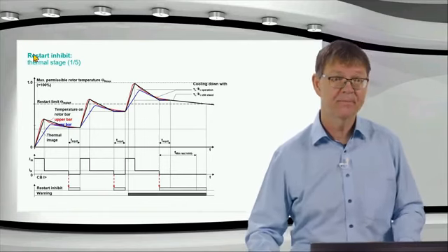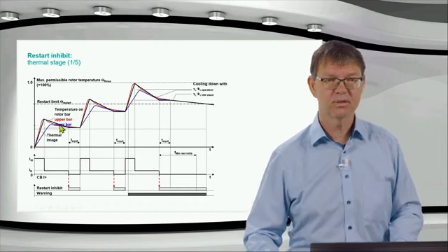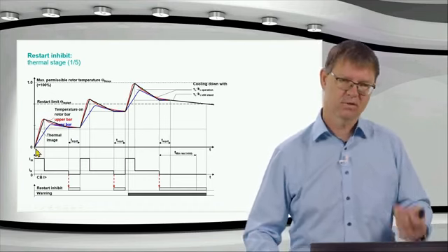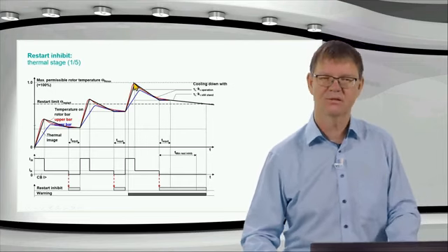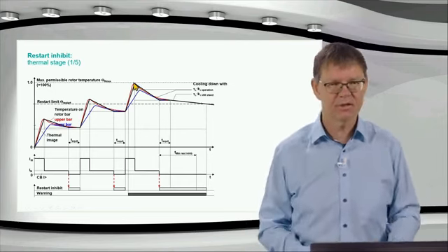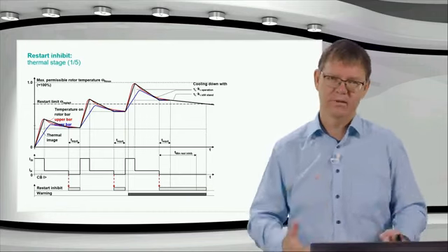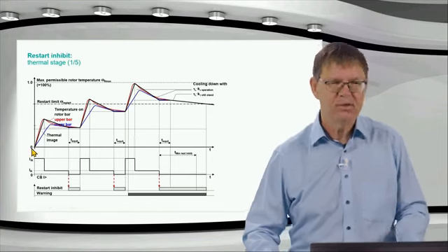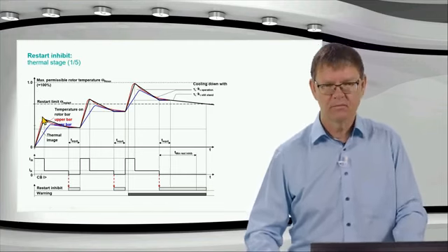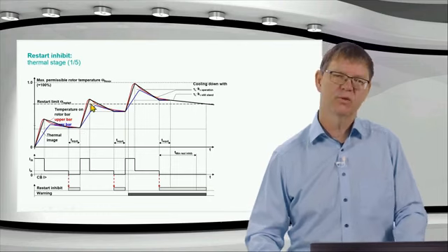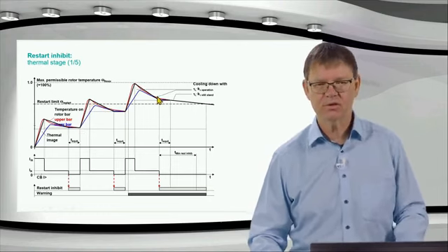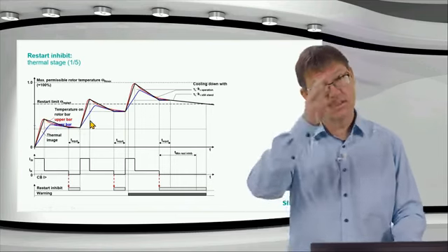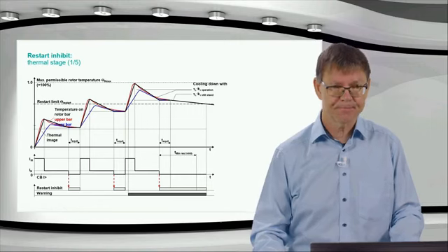And what we do is basically that we now calculate our temperature so that I get the maximum temperature 1 after the 3 starts. So because it's 3 starts from cold, in that way it's scaled, let's say, or we dimension the function, because we enter the data which we get from the motor manufacturer. And of course, we do an approximation, as already said. We have here this black curve. This would be the curve which we calculate. These are all E functions, although you might not see it now here really in that diagram, but it's a starting E function and a falling E function here.